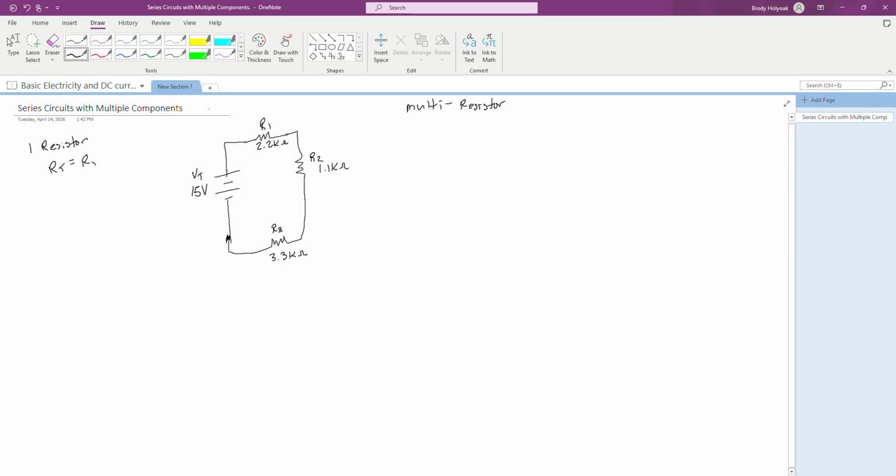So when we go through here, if I'm wanting to push electrons and I'm wanting my current to flow, we go using conventional current flow. We go from the positive through R1, through R2, through R3, and when we get back here to our negative pole, that's how much resistance we've had to travel through, and that's how much is going to slow down all of the electrons. So my R total has to include a combination of all these resistances. So to push from one side all the way through, I'm going to get R1 plus R2 plus R3.